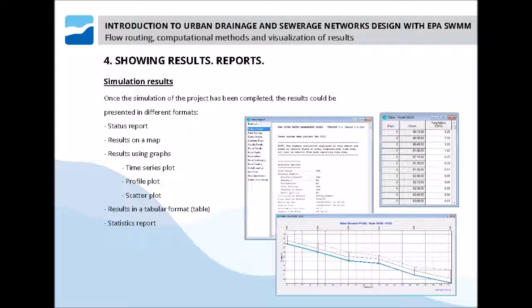Because the first time, honestly, it is more than usual to find an unexpected element which will make us review the whole simulation. That is why we will resort to reporting and warning messages from the storm water management model to see where errors occurred and where we have to correct some data in the project and start the simulation over. We will repeat this process as many times as necessary until our simulation is successful. And once it is, here is what we shall do.